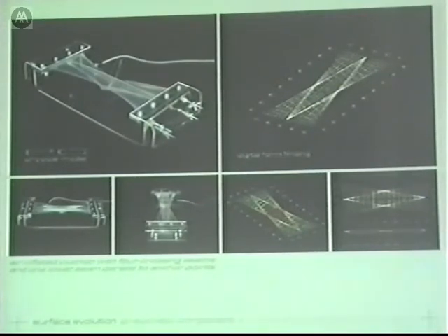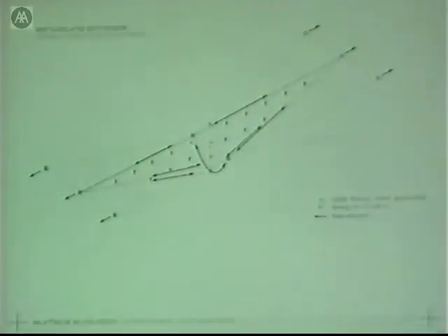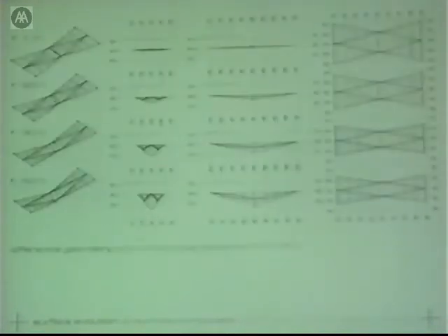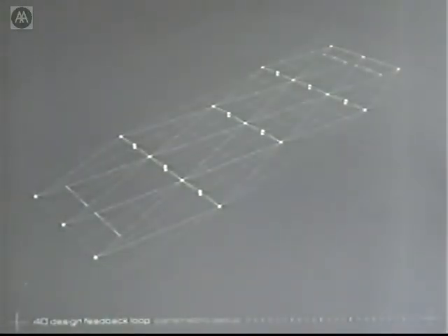And I think that is what George already outlined, is that you actually create, through an additional seam in that case, a shorter and a longer surface, and thereby, during the inflation process, the membrane gets pre-stressed and it's actually forced into a 3-dimensional shape. So that's what you can see in that sequence. Depending on the sag that you allow at that seam and the pressure of the inflation, you can strategize the change in geometry. This can obviously then be further exploited by multiplying the component into a local multi-chamber system.